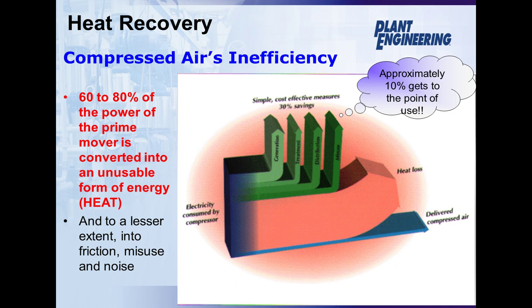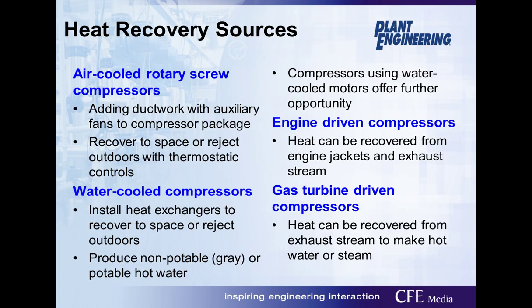So if you can take advantage of heat and recover that heat, you can at least make the system a little more efficient and take advantage of stuff that you have to actually pay to get rid of. You have to run an intercooler and an aftercooler, and whether it's water cooled or air cooled, you have to be able to reject that heat when it goes into the system.